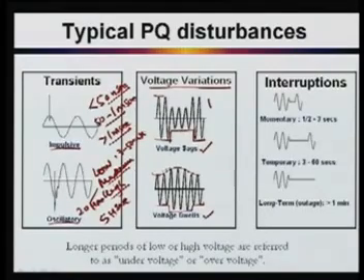Here the voltage dip, this magnitude, how much dip? If your voltage is between 0.1 to 0.9 per unit, then it is called voltage dip. Here, why is it 0.1? If this is less than 0.1, then it is called an interruption, because in a sudden short circuit the voltage is almost 0. 0.9 we have mentioned because a voltage more than 0.9 per unit is sometimes known as the normal voltage.